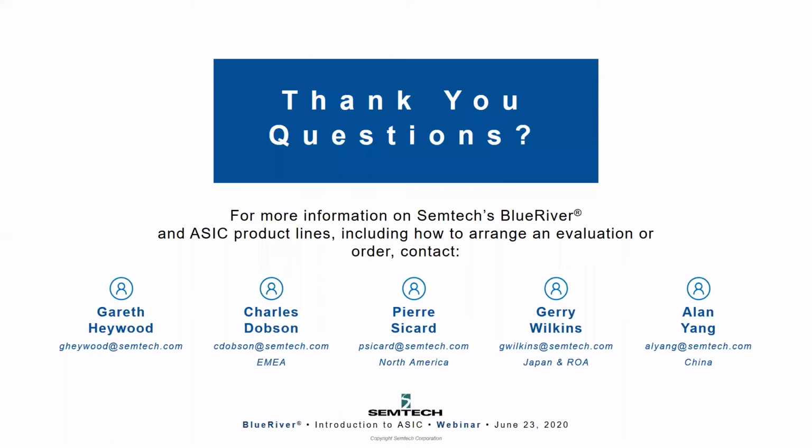We find that if you compare to, say, HDBaseT, for example, which is a proprietary PHY, their crosstalk and alien noise rejection performance is extremely poor, because it doesn't include all that advanced DSP processing that many 10 gig PHY manufacturers have spent many, many years and man hours perfecting. So we want to take advantage of that. Also, we want to be agnostic to the physical connectivity. That's why, for a lot of applications in the future, we see moving towards fiber. We allow you to connect either through a fiber SFP+ module or a standard IEEE compliant 10 gig PHY.